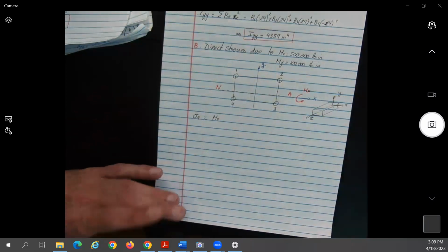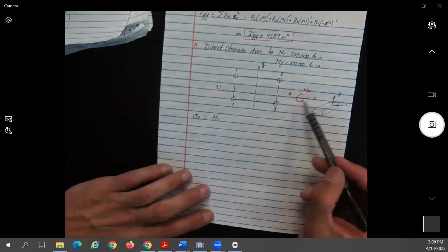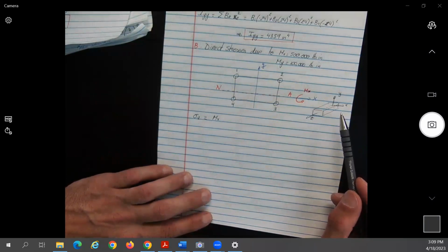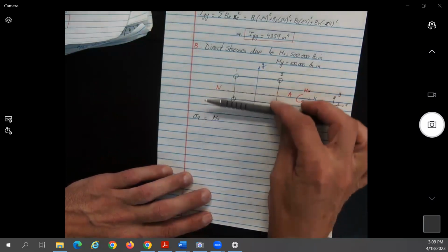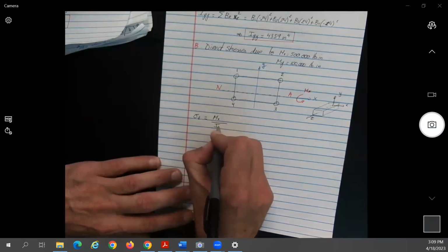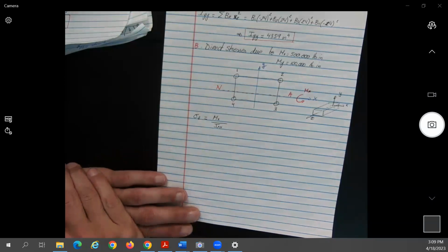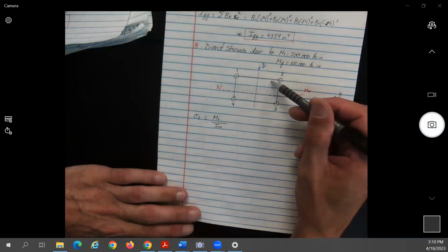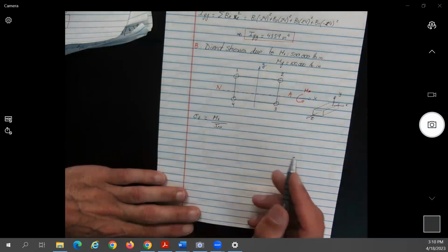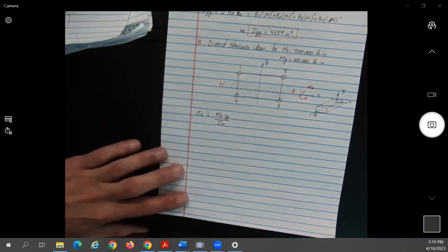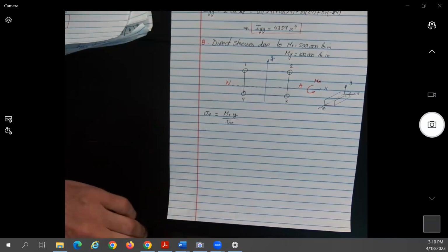See, I don't memorize the equation. It's just understanding. So if this is the moment, this will be bending about what axis due to this moment? Will be bending about the Ixx or about the Iyy? Will be bending about this axis, no? Due to this moment. So what is going to resist the bending? Ixx. And now we can find these stresses at what locations? 1, 2, 3, and 4. So what is the distance from the neutral axis to 1, 2, 3, or 4? In what direction is it? Why? You see, you don't need to memorize the equations. With understanding, you get them back.